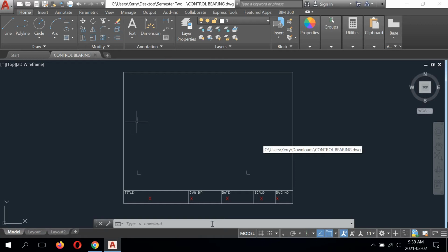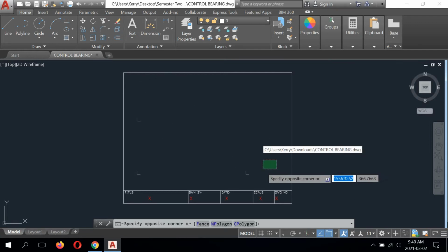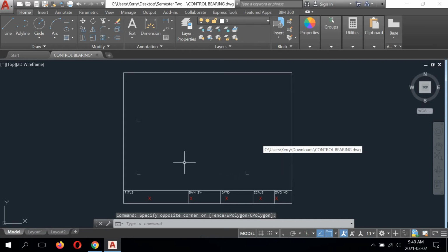All right, so the border looks the same as what we've seen already. The only difference is we see 3 origins now instead of 1. And this is going to allow us to draw the views in the correct position and allow the correct spacing between views and make sure the views are centered within the drawing space. So our front view is going to go in the bottom left, our top view is going to go above it, and our right side view is going to go to the right side of the front view.